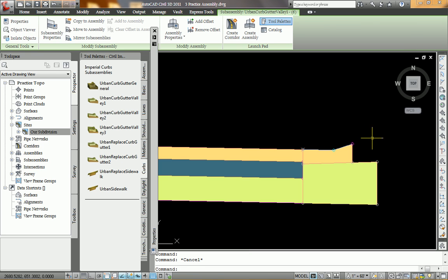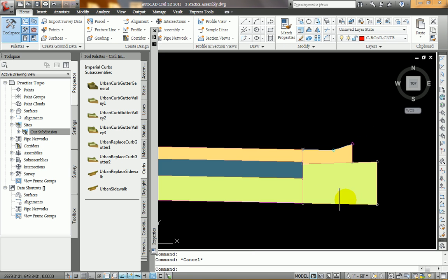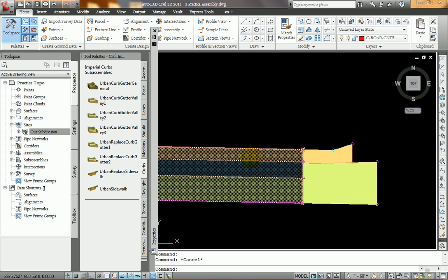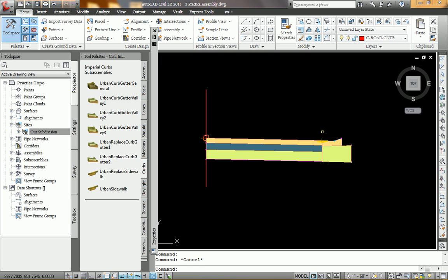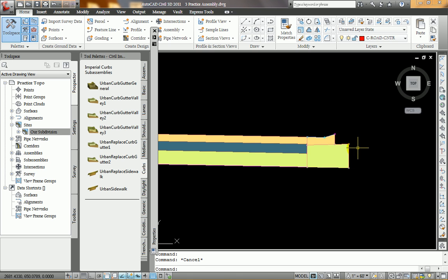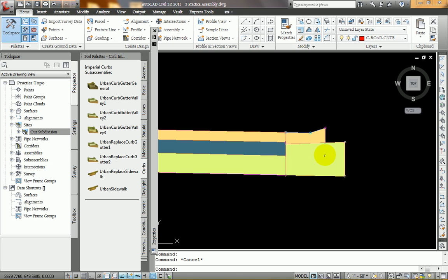At the end of the day, what you want is a smooth, continuous line. Now, ideally, you'd probably make your curb a little bit thicker and drop this line down to line up with this one. Or you'd have some different layers of your cross-section here. These are some pretty thick layers as far as cross-section goes. Either way, though, you want it to line up across the top, line up across the bottom, and you definitely want that subbase to continue out underneath your curb, wherever that's at.